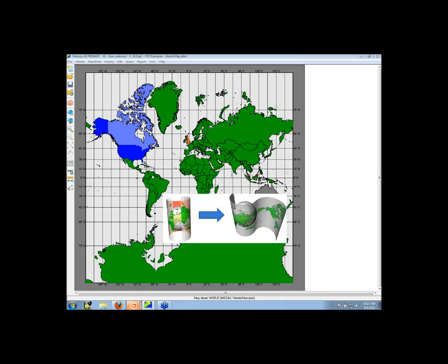So this is just an example of why you'd want to use the right coordinate reference system to create your maps. This might be okay for use around the equator, but when it comes to things like defining country boundaries, you're not going to want to use such a regional type of projection system, because the lengths are going to be very, very different. Say you're trying to define the boundary between Greenland and Canada, you're not going to want to use this world Mercator, this cylindrical type projection system, because these lengths are going to be horribly distorted and completely inaccurate.